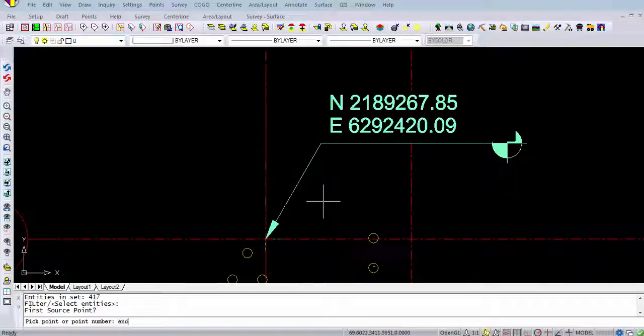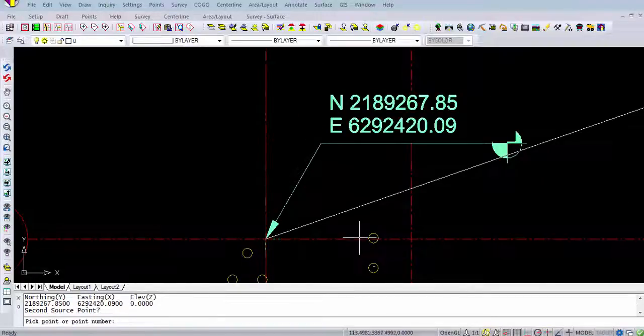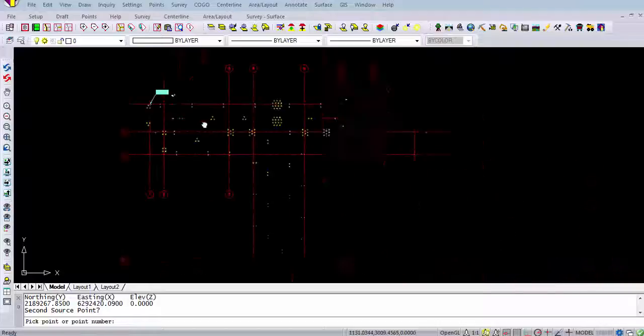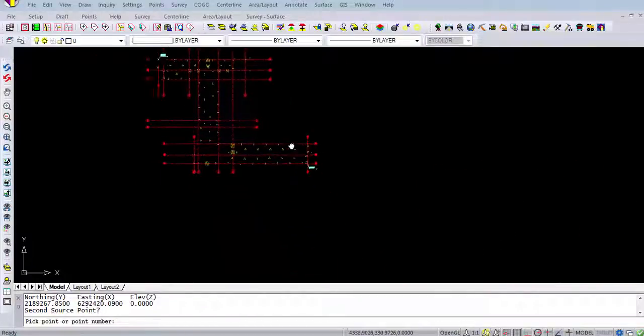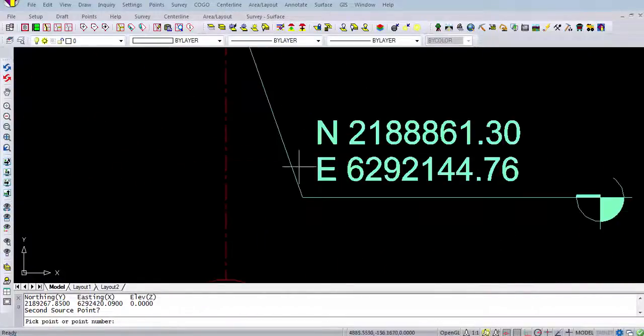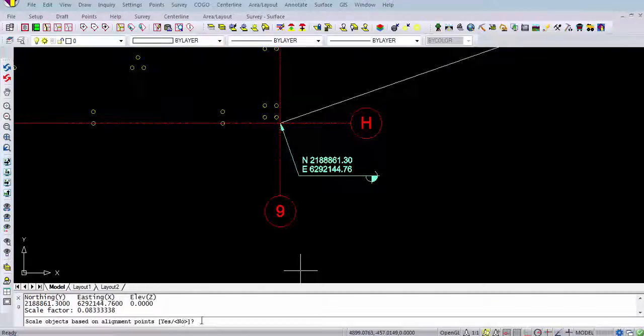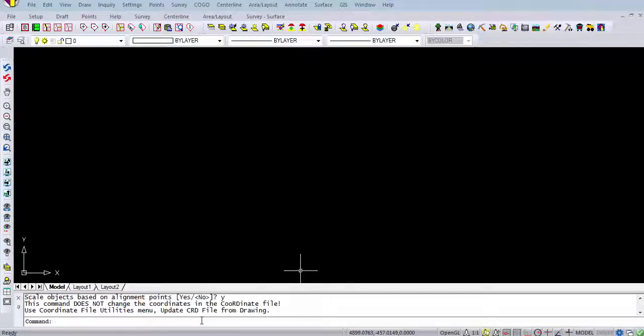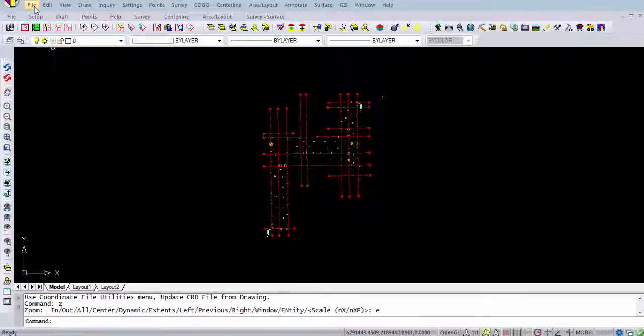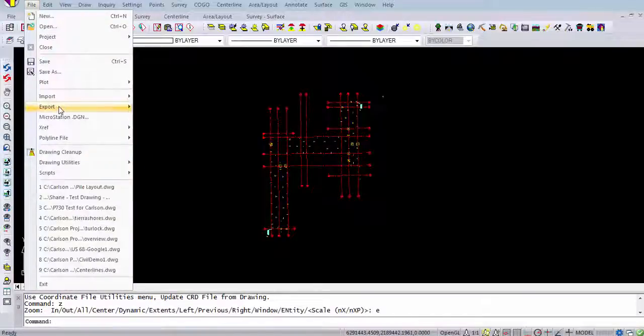You can see the coordinates are labeled. Well, I've already just got those saved in a buffer, so I'm just pasting them in quickly here. So you're picking the source point by the endpoint snap here, and then I'm going to paste in the coordinate pairs. This is easting, northing in the order, and now it's going to scale it, and you see everything disappeared. Let's zoom to the extents. There it is. You might be able to tell the orientation changed.